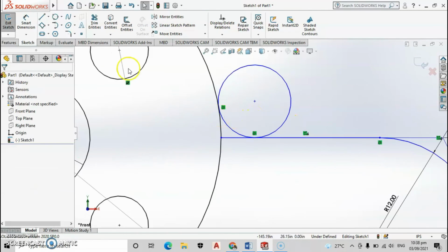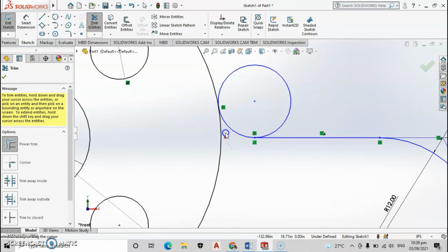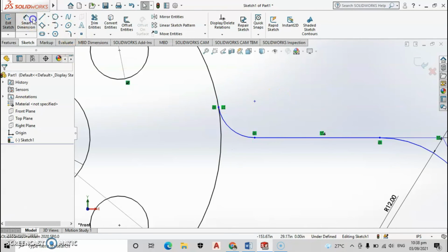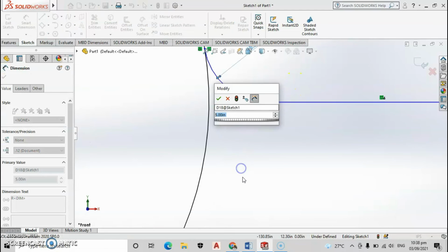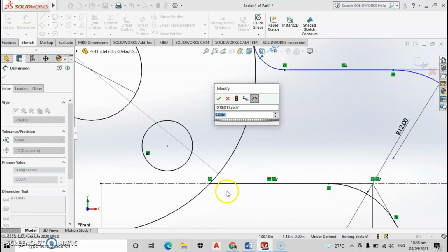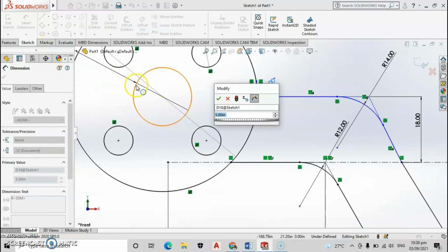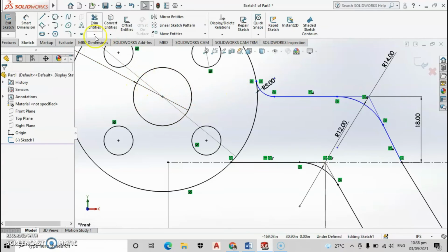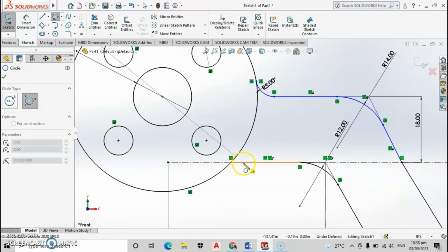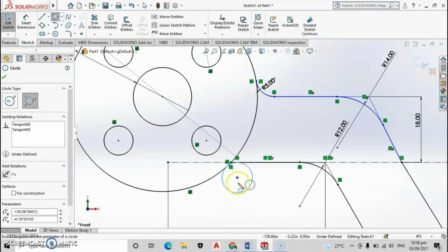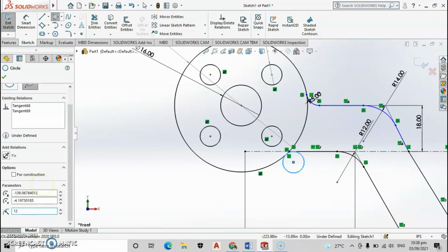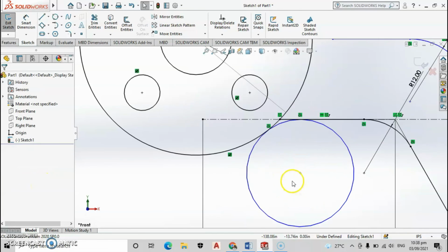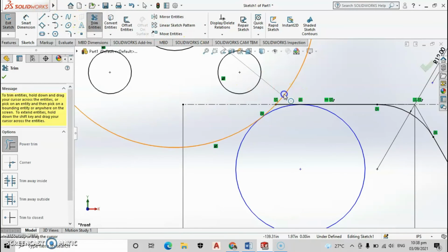You can perform fillet in both circles, and in circles and lines. So that part, I'm thinking again, clicking the circle and clicking the line, and knowing that we perform circle, trimming it. There you go, smart dimension. There you go, radius 5, and click enter.